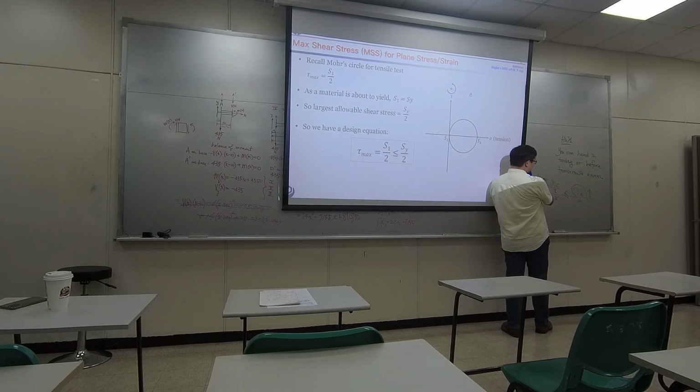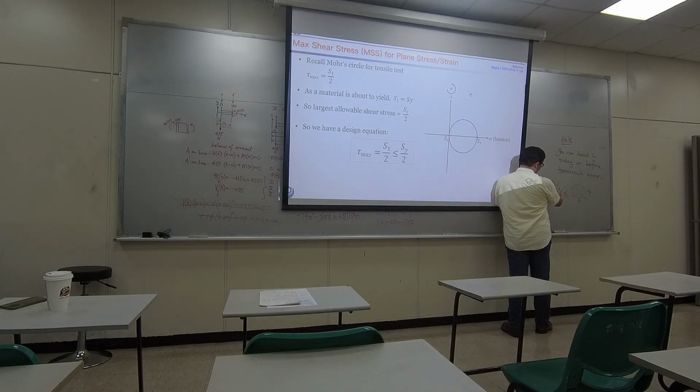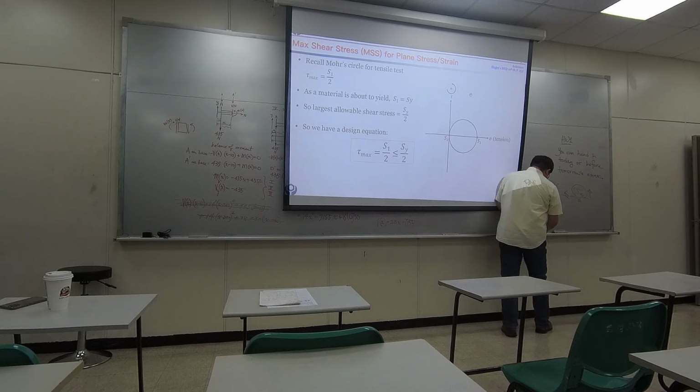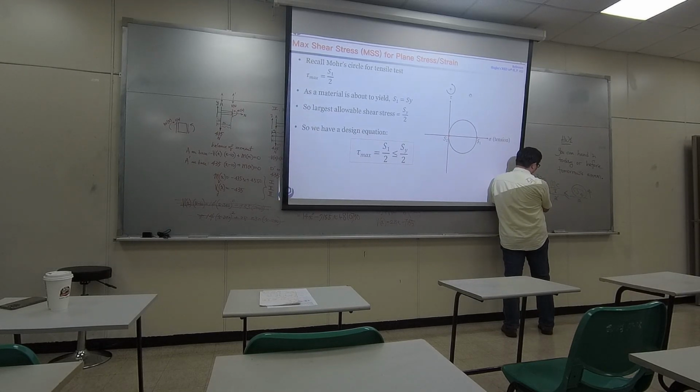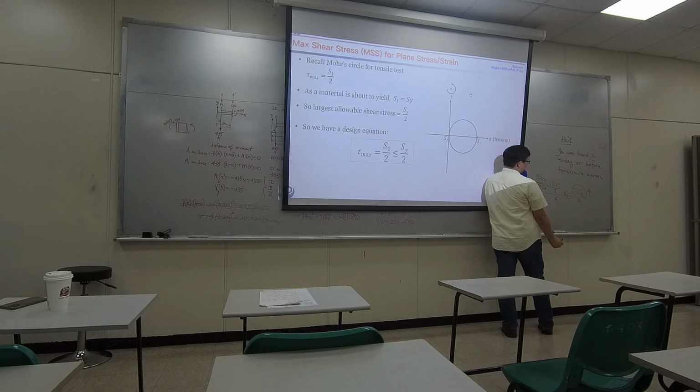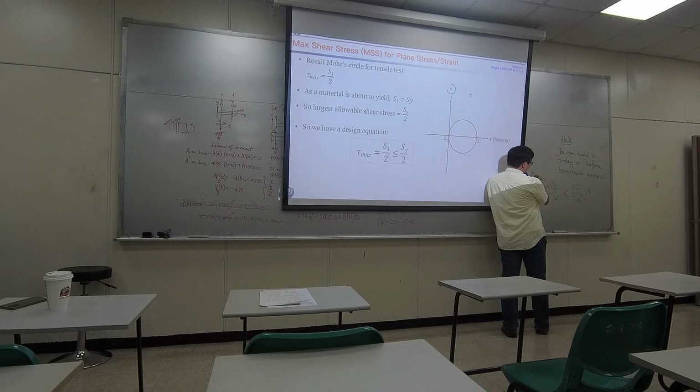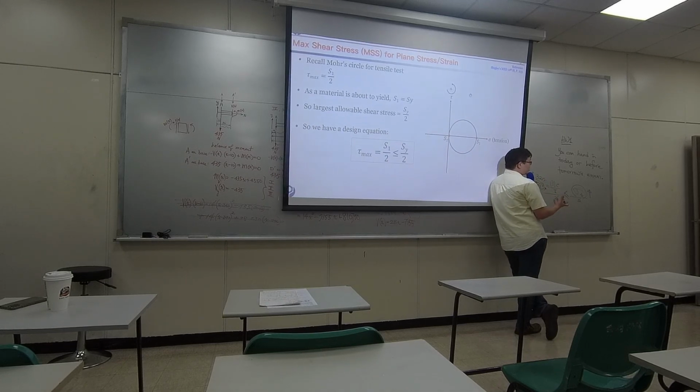So if you convert this equation into the equation for a shaft, then you basically merge the radius or diameter parameter together. So in this particular case, if you enlarge the diameter, the overall left-hand side will decrease. When the overall left-hand side decreases, that means the stress applied to the material will be reduced. And of course, it will be safer.